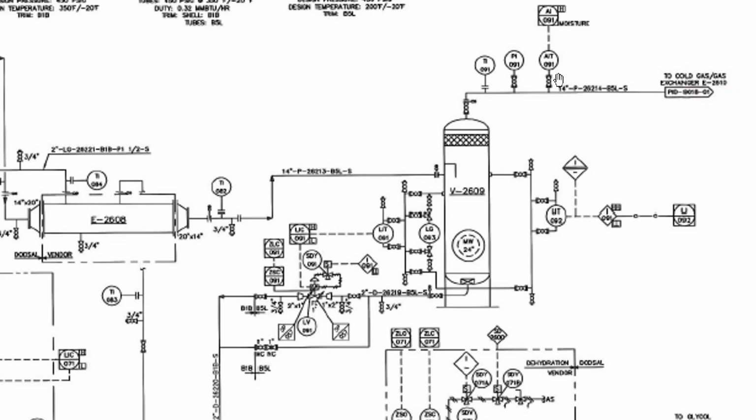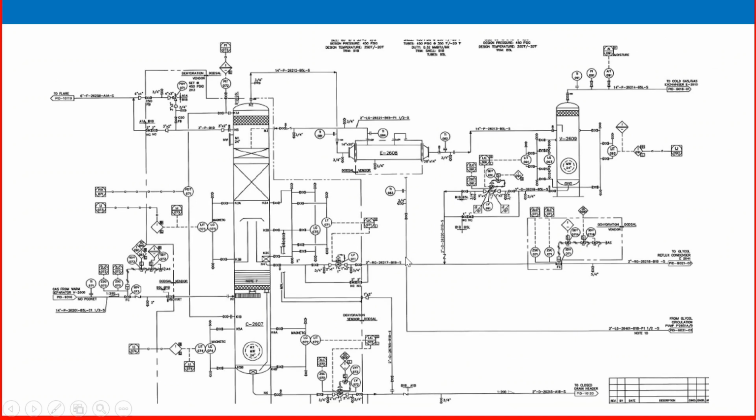So sweet gas is readily available here. And here see, the H2S analyzer is also there. How much H2S is there? That is the AIT, the analyzer. So this is the typical P&ID of the absorber. So let us discuss various process parameters affecting the performance of the gas sweetening process, mainly in the absorber. Just keep this one in pause mode and review each and everything, and if any doubt is there, just put it in your comment box, then I can answer in detail later.